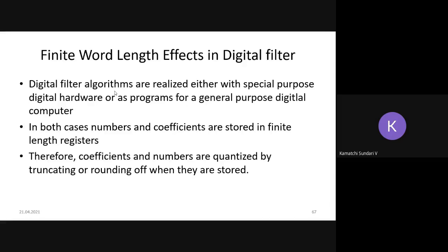In this quantization procedure, depending upon how many quantization levels I have, I will have my lowest value and highest value, right? If I have a greater number of levels in my quantization procedure, then I will experience less error while doing the rounding process, the quantization process, right? But if you go for more levels, then I have to represent each data with a higher number of bits. That is the concept.